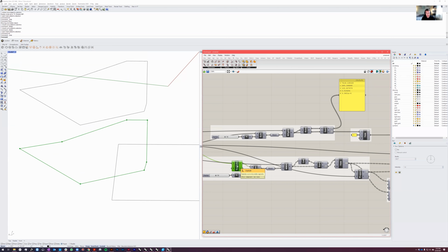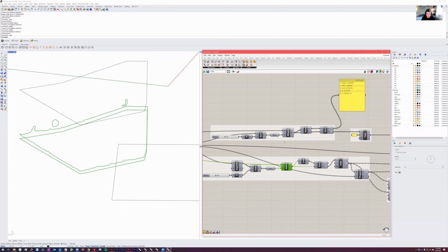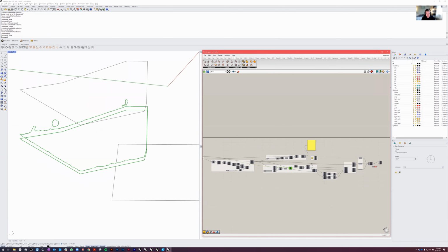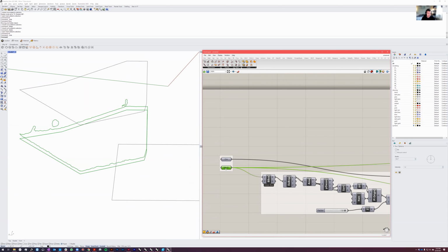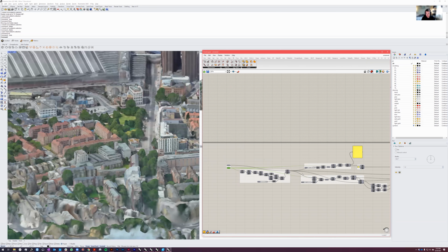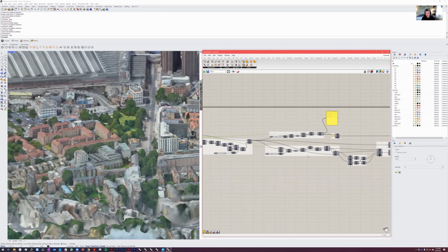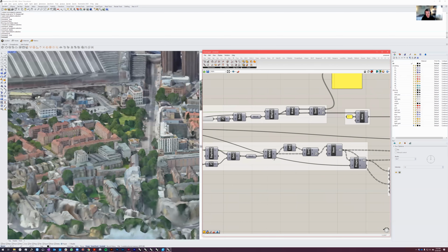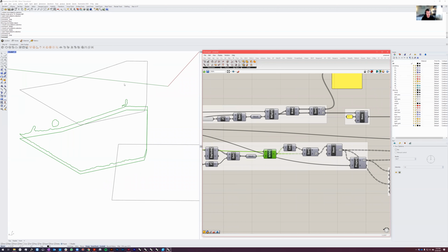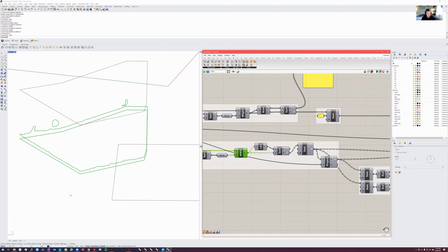In this case, because I exploded the curves, each of these lines of the explosion is going to be a mesh that's extruded. And then what I'm doing is I'm finding the mesh intersection. So I'm intersecting between the mesh we imported, the photogrammetry mesh, which is actually the full deal, not the trimmed. And I am intersecting with the meshes that we just created. So those are giving me these intersection lines. Each of these now is a line, and you'll see I now have 18 lines that I'm interested in, or that are created from this.